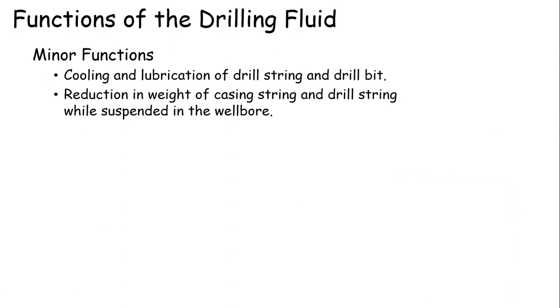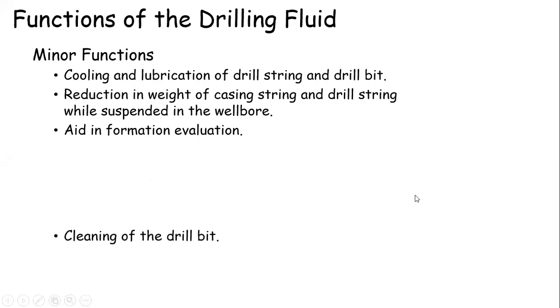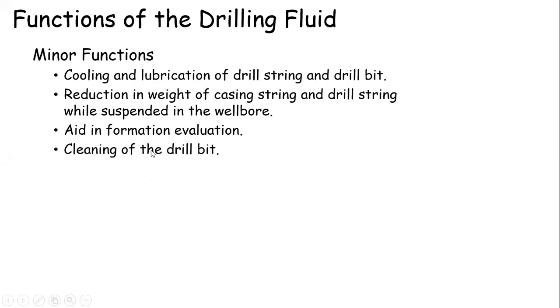We have a lot of components that are joined together to form the drilling string. Then this is suspended within the wellbore. So the drilling fluid helps us to suspend the weight and reduce the weight of the casing string in the wellbore. It also helps in formation evaluation and cleaning of the drilling bit from other mud particles that are inside the wellbore.